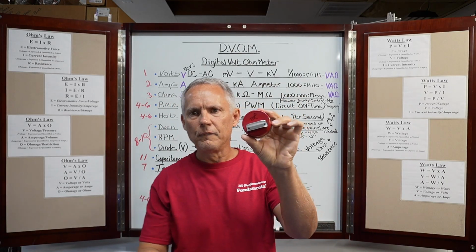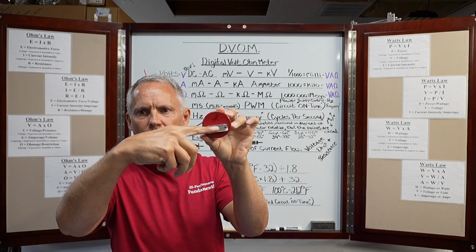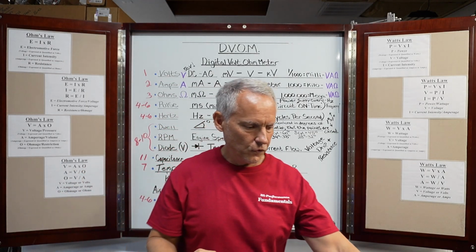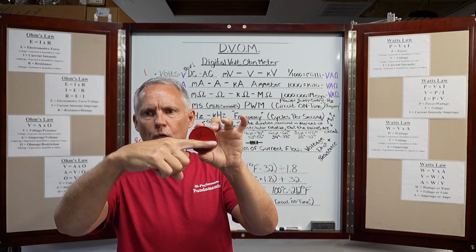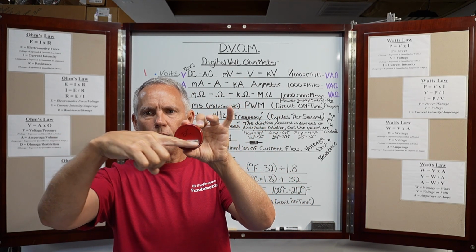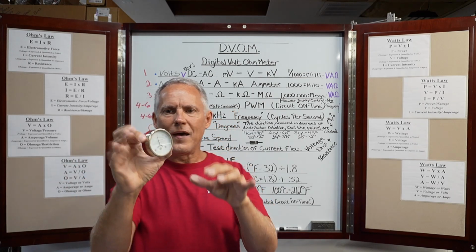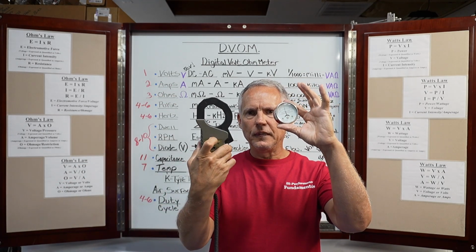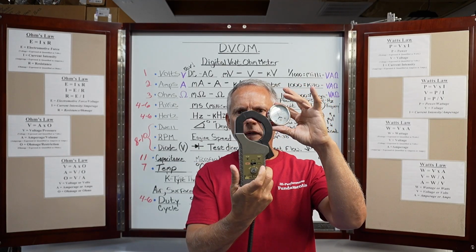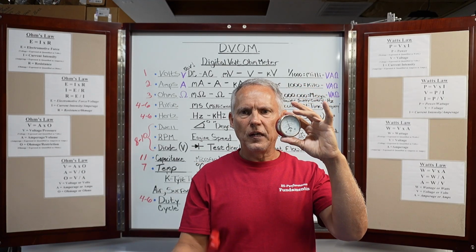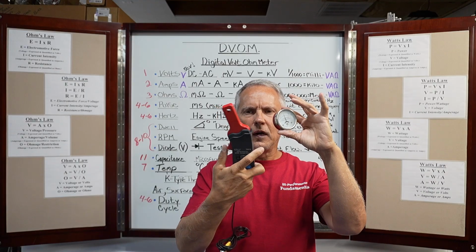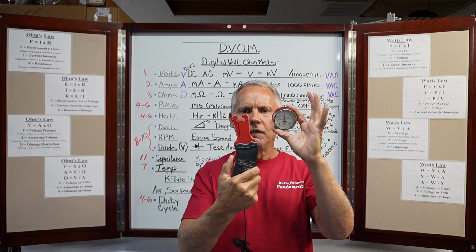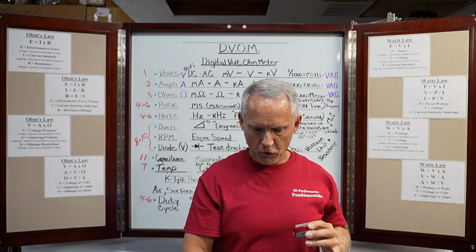And you look on the back here, you'll see this little groove right here. That lays on the wire, just like this. This one's exactly the same way. It lays over the wire, just like that. Current flowing through the wire is measured by the inductive ammeter. This is inductive, this is inductive, this style, all inductive. These go around the wire. Open that up, slide the wire right through it, like that. Clamp onto the wire or over the wire.